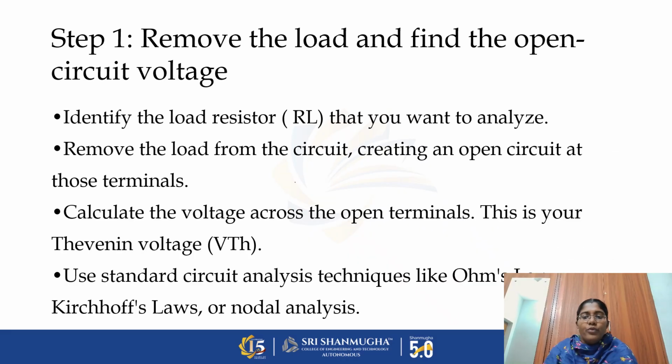We need to follow a few steps to find the Thevenin's equivalent circuit. The first one is we have to remove the load and find the open circuit voltage. So in step one, we have to remove the load resistor. The load resistor means the resistor across which we need to find the voltage, or the current flowing through that resistor. That is the resistor we want to analyze, so it can be identified as the load resistor.